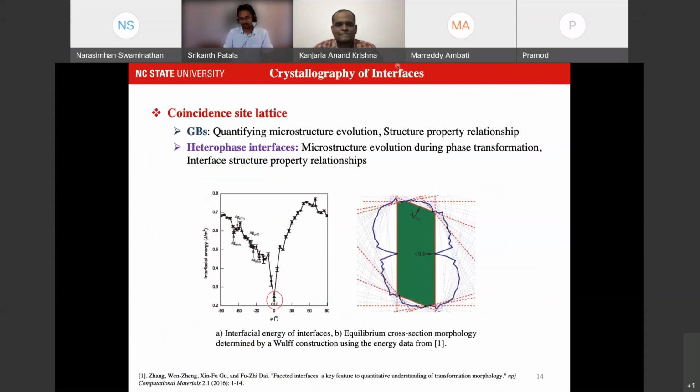Right. Good question. So low symmetry systems, let's not even go that low, let's say hexagonal. There are CSL relationships that are perfect matching, but there are also, if you're aware of this terminology, common CSL and specific CSL. So it depends upon the CSL number. If you're going to higher order CSL, then you do get cases where the matching is not perfect and you have to apply distortions. And that depends actually on the c/a ratio in the hexagonal system.